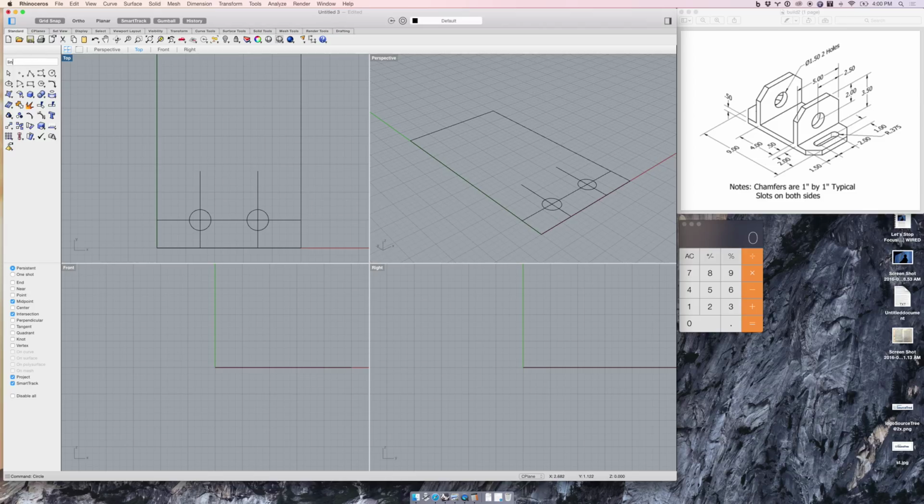So what I'm going to do is do line. And I'm going to connect midpoint intersection. If you're not getting these same snaps turning on, you need to check your O snaps on this side. Intersection, intersection. Now I'm going to introduce you to the trim command.